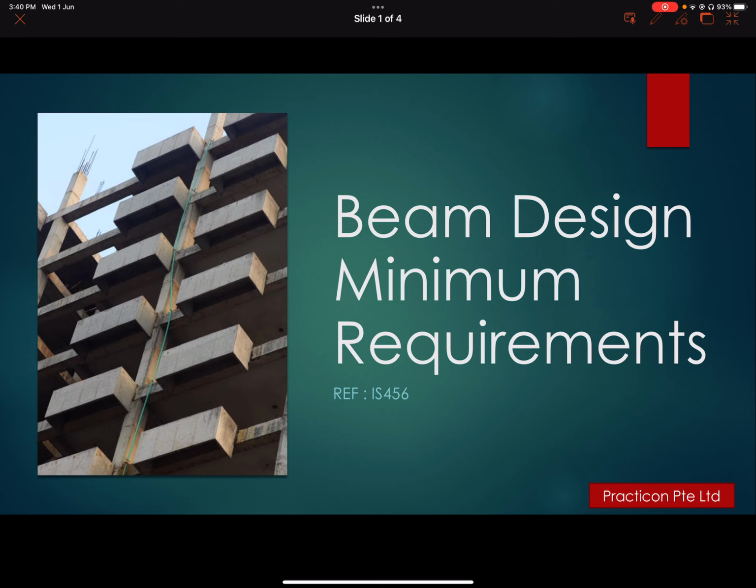We cannot simply accept that two 12 mm bars are sufficient because the load is very less. Due to several serviceability and strength criteria, the code has suggested the minimum requirement that needs to be provided for the RCC section. What are those? We can discuss in this chapter.